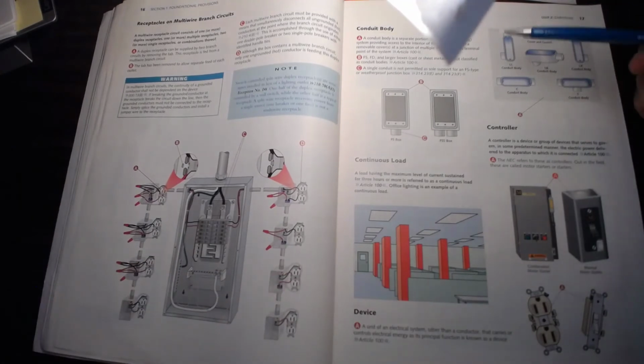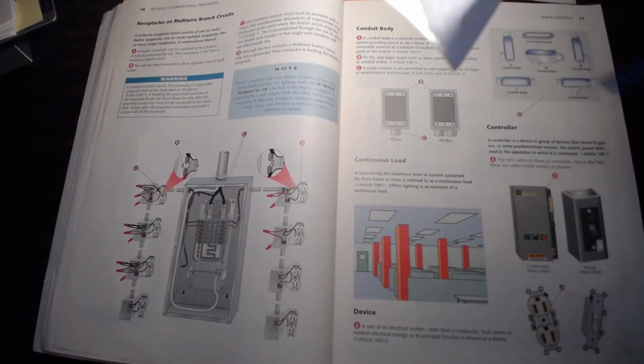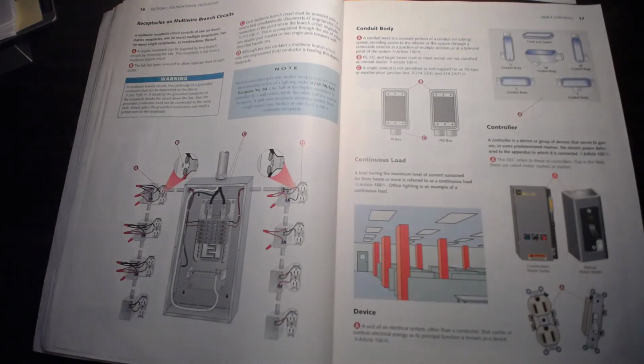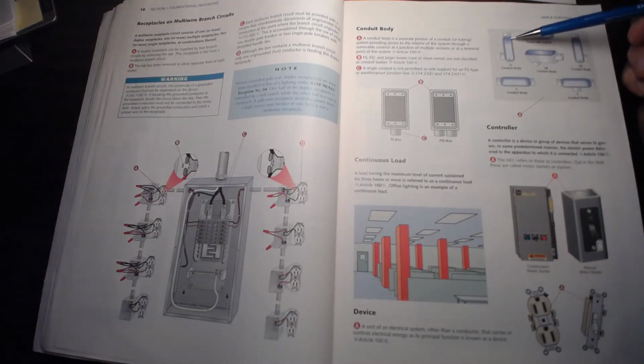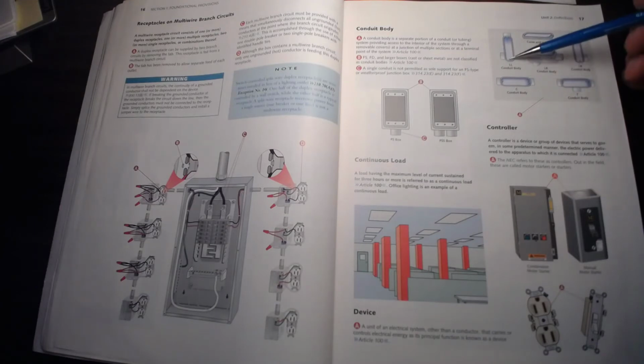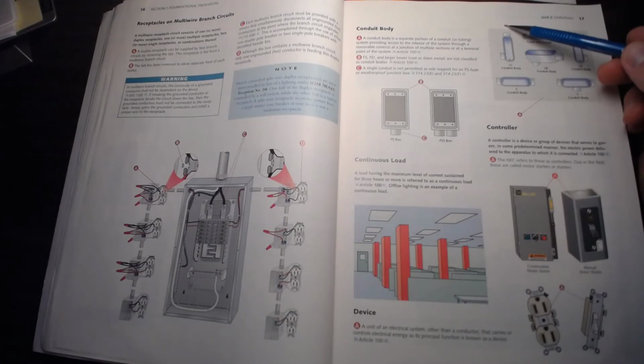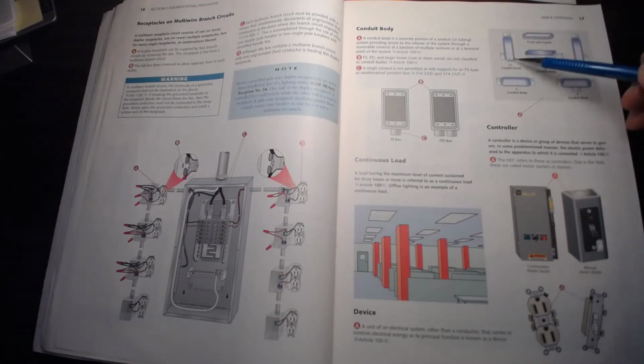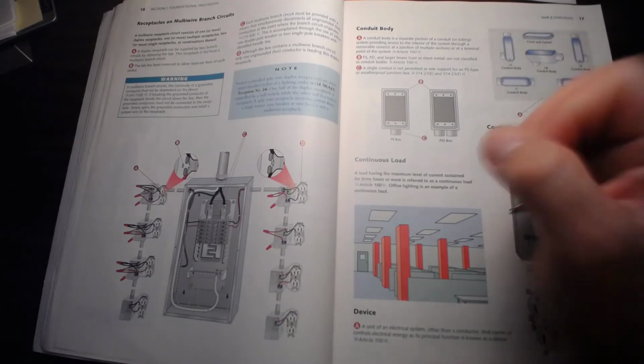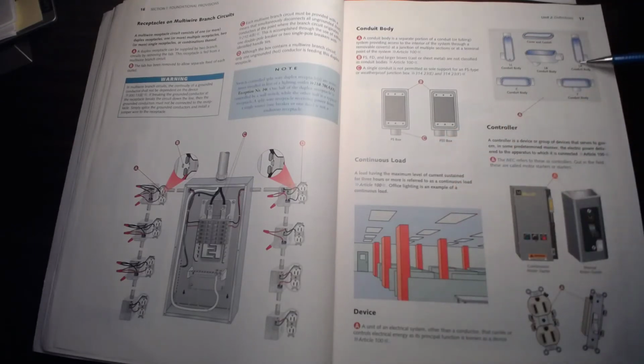Conduit bodies. This is another one that's very important for us to understand. When we have a conduit body, we have a device or a connection that looks like these over here. The easiest way to remember an LL is if you hold the conduit in your hand like this, pointing out straight ahead of you, then the opening would be on the left-hand side, an L on the left. And if you hold it in your hand like this, that is an L on the right opening, and an LB is an L on the back.